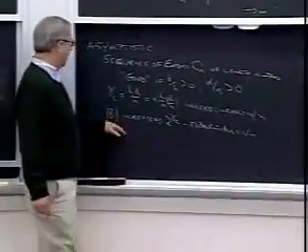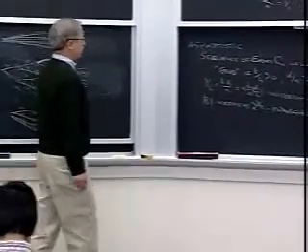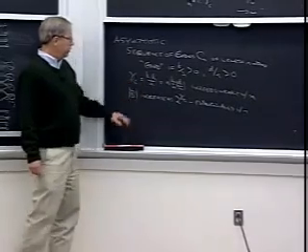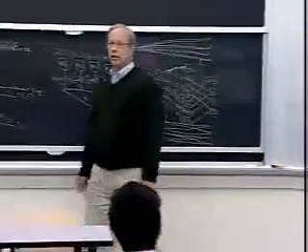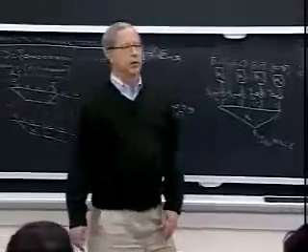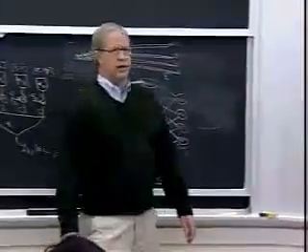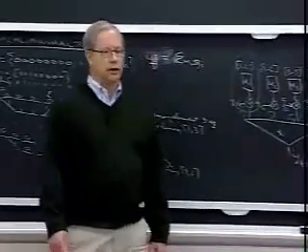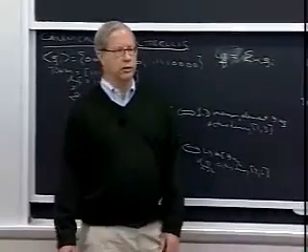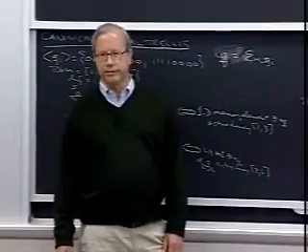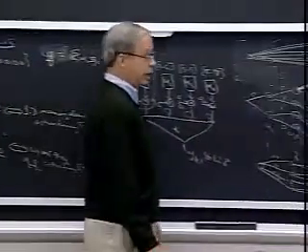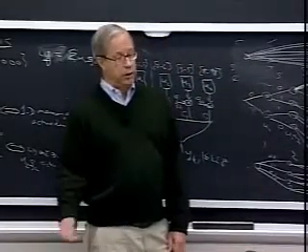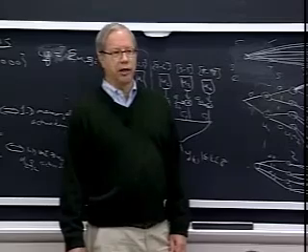We have, however, another way to go. Do we really need the nominal coding gain to go to infinity? If we go back and remember the name of the game, the playing field that we're on, at least in the additive white Gaussian noise channel, we found the distance between uncoded and the Shannon limit was some finite number. Something like 9 dB at a 10 to the minus 5 error probability, larger at lower error probability. So that's the maximum effective coding gain we can ever get.